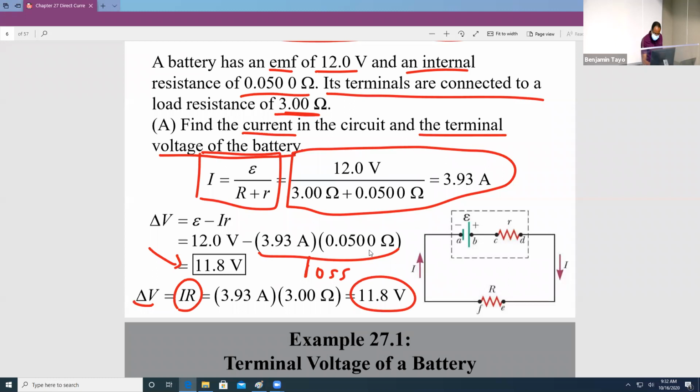because we're saying that, so what this says is that this battery, think about this battery as supplying E minus I times r. So that was the terminal voltage just by delta V. And the reason is because we have this internal resistance here. Okay.